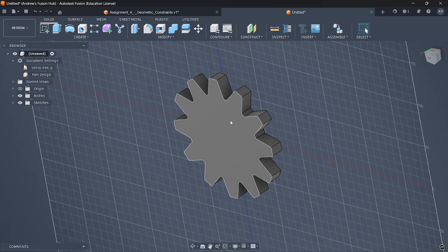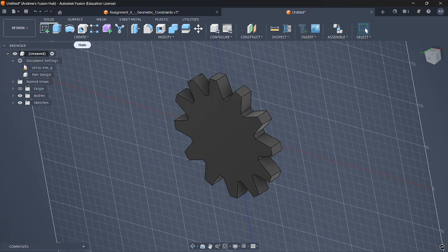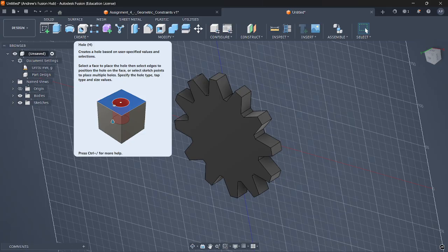That, or they may charge you more for something that you didn't need. Or they won't even do anything if there's not enough clarity. Yeah, or they might just reject your part, right? So the hole tool is really important because it gives the machinist all the specifications of the hole. You can write it manually, but that is kind of annoying, and it's typically a lot easier just to use the hole tool. Especially when you get into more complicated holes, like, oh, I want a counterbore this deep with the bottom having threads for a certain bolt, right?